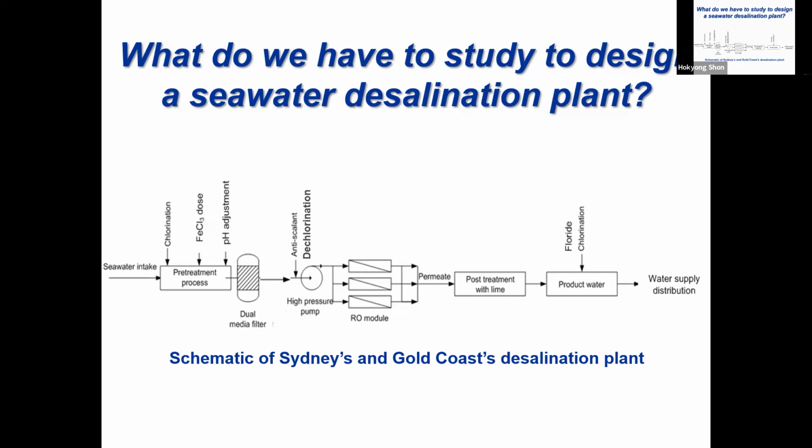After that, the reverse osmosis membrane is a polymer. So if chlorine is passing through this membrane, this membrane is a polymer, so it is oxidized. So the oxidation will damage your polymer membrane. It's like a plastic membrane. So we want to dechlorinate it, so remove the chlorine and oxidant. That's the reason you can have a more long-term operation of a reverse osmosis membrane.